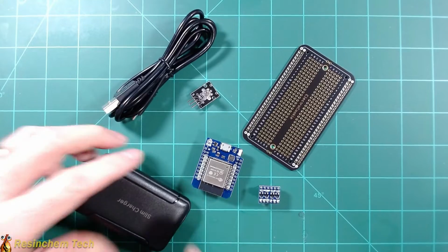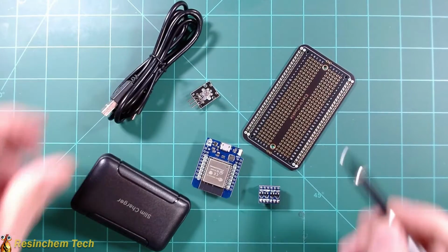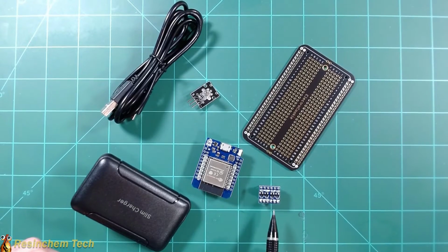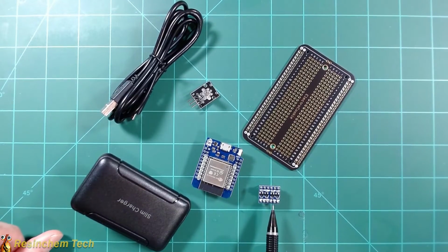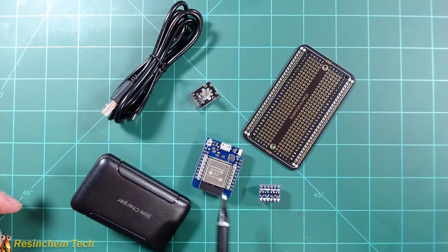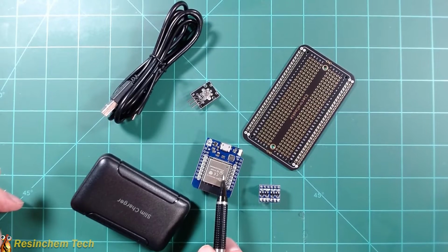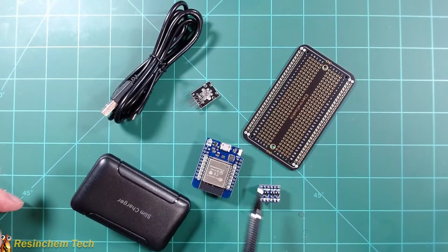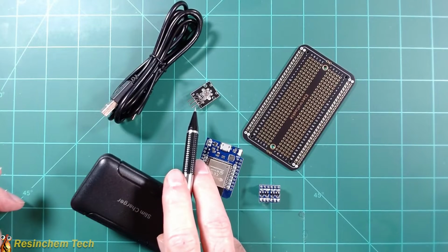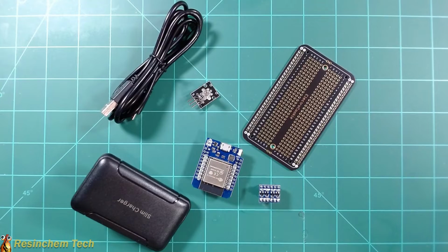Need a micro USB cable. I'm going to mount this onto an Electro Cookie prototype board. And there's one other part here that if you've done any LED projects, you've seen in my LED videos, you'll recognize this as a logic level shifter. Now this is optional, but I did find during my range testing that by boosting the 3.3 volt signal from the ESP to the 5 volts before going to the LED actually did help my range a little bit, but that really is entirely optional and you could probably get away without it.